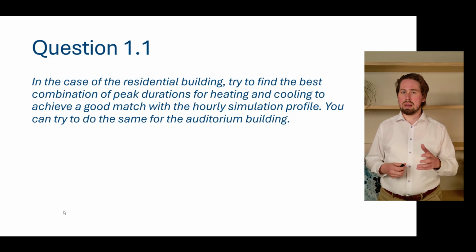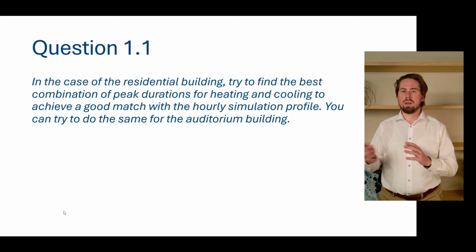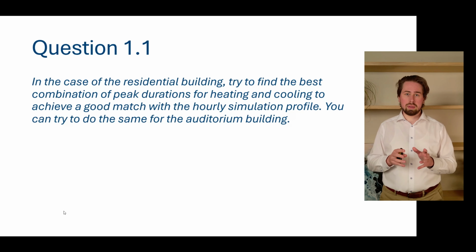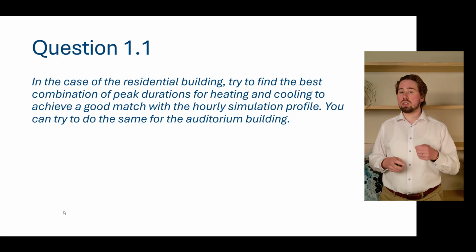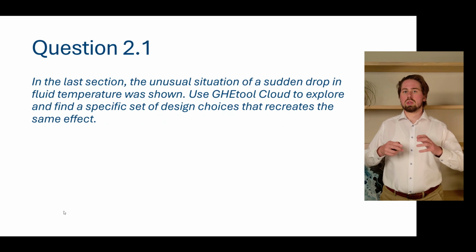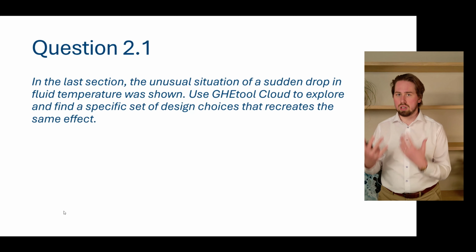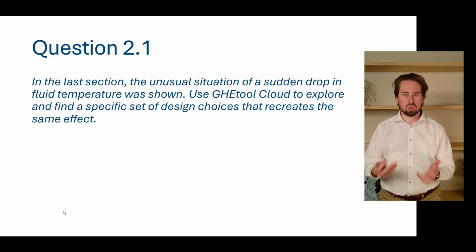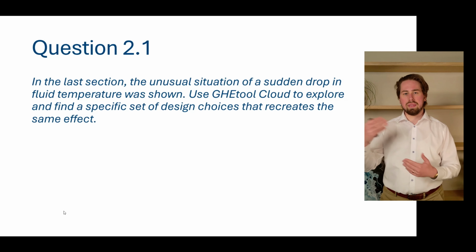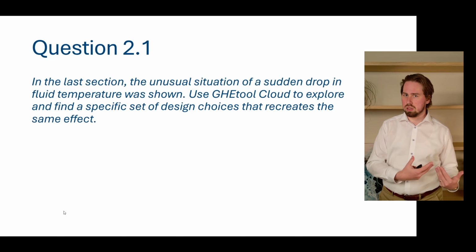And this question is all about how you can convert your hourly simulation towards a monthly simulation just by playing with the peak durations. Now, before showing you this answer in GHE2, I also want to introduce the second question, because there we were talking about the variable fluid properties and that we do not work with a constant viscosity and Reynolds number throughout the whole simulation period anymore in GHE2, but you can actually update the viscosity at every hour of the simulation, and this also had a quite tremendous effect on your results.